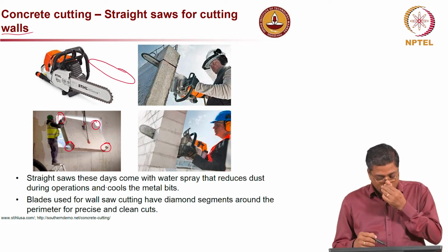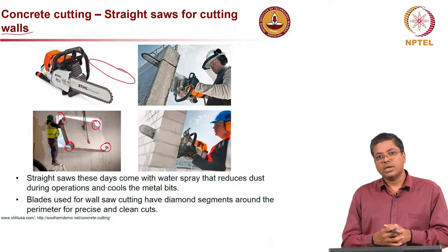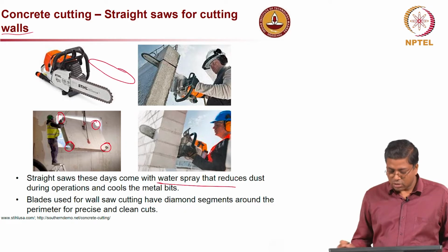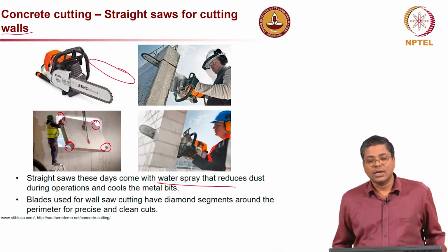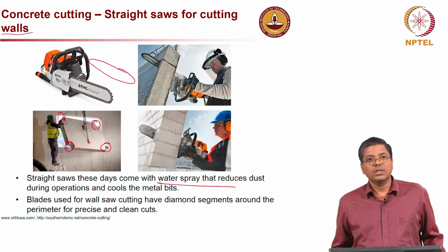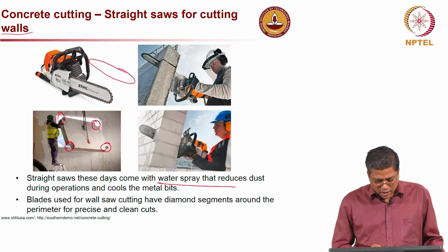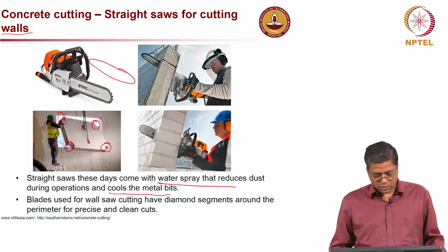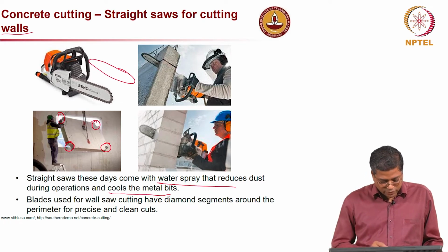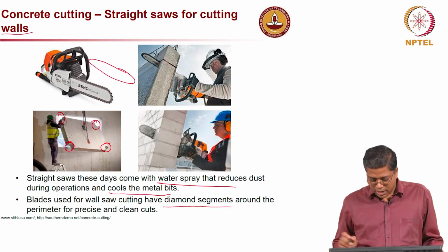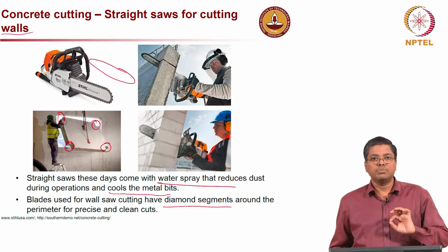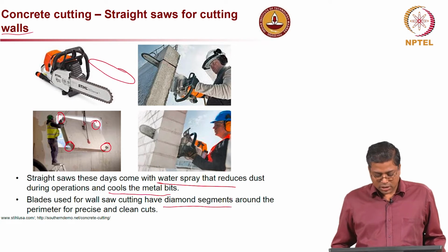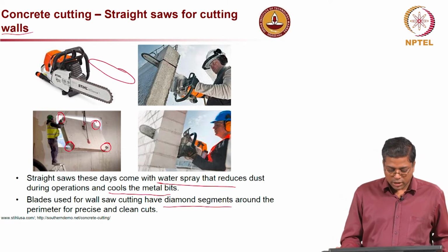Now, when you talk about cutting, there is always a possibility of dust coming. So, these days there is also water spray that reduces the amount of dust flying during the cutting operation, and at the same time it also keeps the metal bits very cold, so it does not wear off very fast. Also, diamond coated or diamond tips are provided on these cutting tools, so they can really cut through very strong concrete elements.